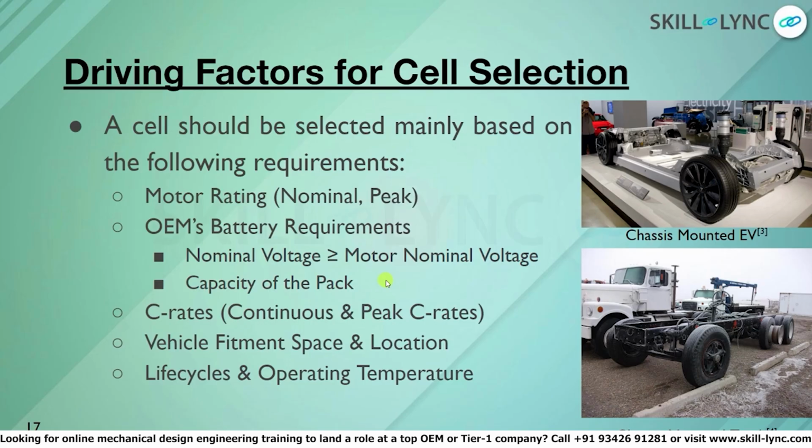That means your motor would be oversized and your battery pack is not going to deliver such C rates. Then the whole performance of the vehicle goes down. So you'll have to understand what the C rate of the motor is, what capability the motor will deliver, whether there is a real need for it or not, and then you choose the right cell for that application. So that is how your peak C rate, peak discharge rate, comes.